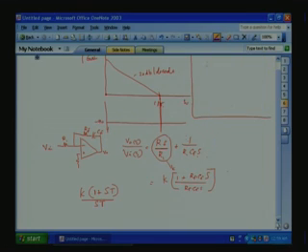If you plot gain versus frequency, you have very high gain at the 0 frequency side, because at 0 frequency S is equal to 0, the gain will be very high, infinity. So, the ideal concept of infinite gain or very high DC gain is possible, same as our PI controller. So, zero steady state error is possible, and at the same time we can also control the phase shift by choosing